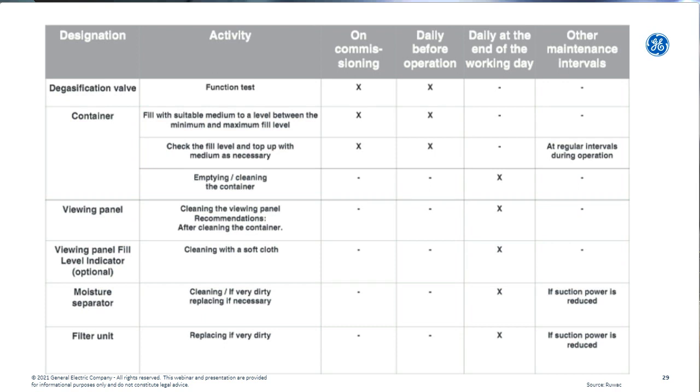And what I really want to emphasize here: do the same and take the steps that you need to do before you operate the wet separators at the beginning and at the end of the day into a simple checklist, post it at your wet separator, and make sure that your operators are doing that. These machines, if they are not treated very well, can pose a significant fire risk to your operation.